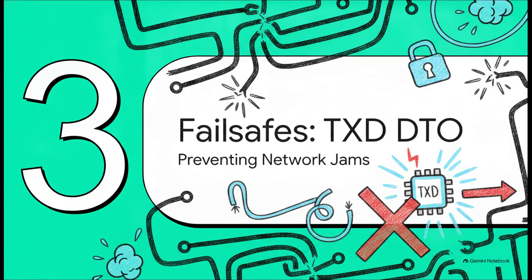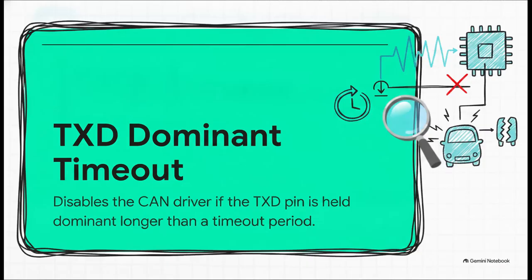But what happens if something goes horribly wrong and holds a transmit pin down constantly? That brings us to part 3, failsafes, specifically the TXD dominant timeout and preventing network jams. This is easily one of the most brilliant failsafes built into the TCAN1042. It's called the TXD dominant timeout, or DTO. Now, to explain the working of a CAN network really quickly, bus arbitration dictates that a dominant 0 state wins out over absolutely everything.